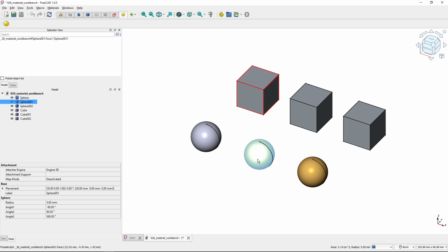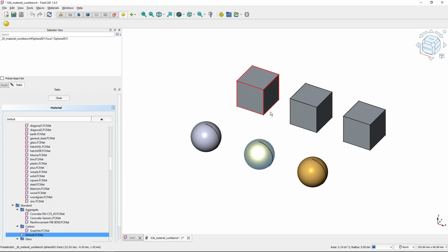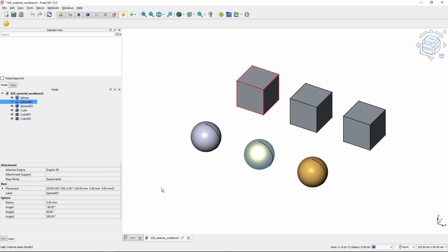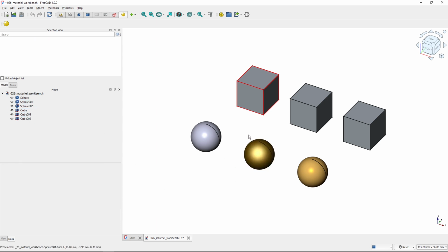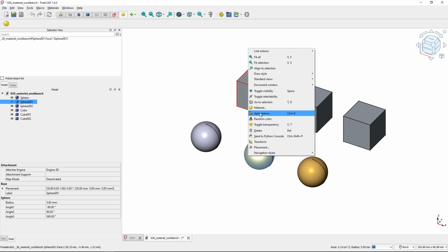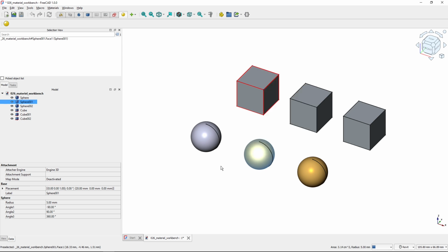But if I check with this gold and change the material again, you can see that it's the default one, and I change it to concrete, hit close, and now I've got bronze appearance and concrete material properties even if I redraw my project. So I think this is a bit of a bug of FreeCAD 1.0, that they don't always synchronize these two channels when you apply appearance and material.